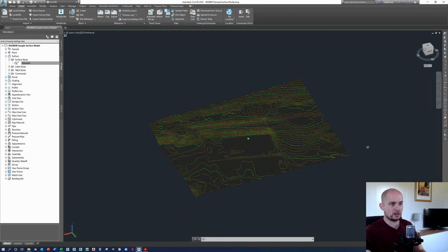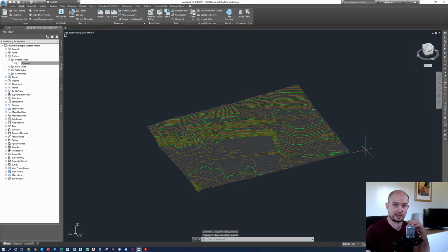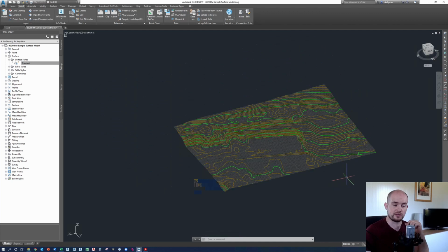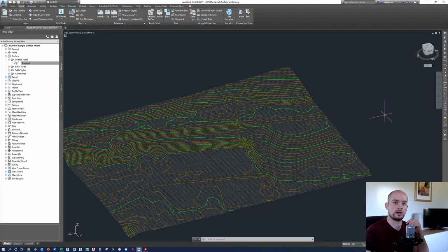And what we're going to go through here is basically how to take in this point data, so that file has in excess of 10,000 points, to create the surface that you see in front of you in Civil 3D. Then in the next video, we're going to talk about how this surface can be transposed into Revit for accurately draping, let's say, a Revit topography over the topography that's been generated. And finally, in the last part, we will discuss how maybe you can cut out the middleman of Civil 3D if you don't mind being a little bit inaccurate and taking the point data directly into Revit, okay?